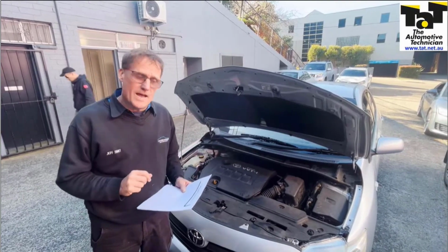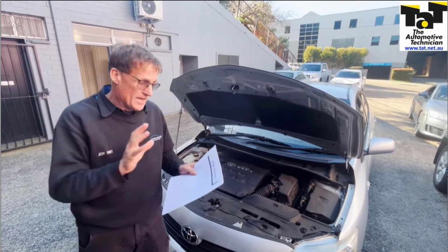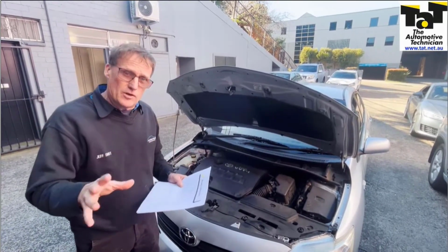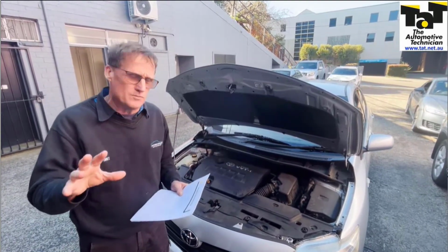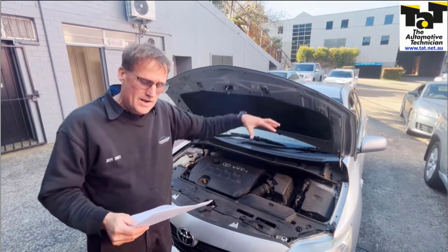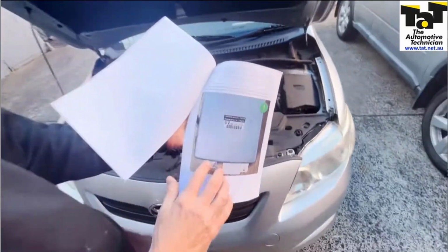Hi guys, Jeff here from TAP. Just had an interesting car in the workshop today which we've now completed, but I just wanted to share with you as we've just uploaded a repair solution for this vehicle. It's a 2010 Toyota Corolla. It's coming in with the electronic power steering fault. I think we've done a video on one of these before where the modules are located up in the centre of the dash area, so the dash pad has to come off. They're mounted up the top there. That's a picture of the actual module that's mounted up on the top of the dash area.